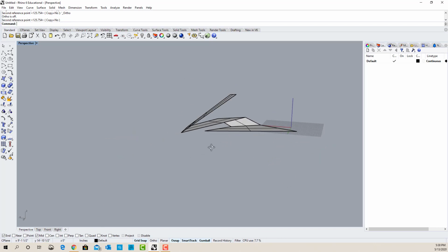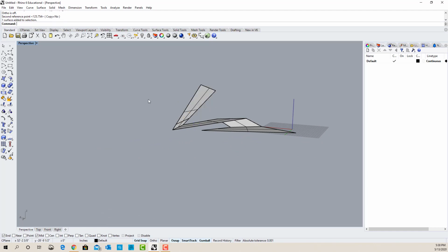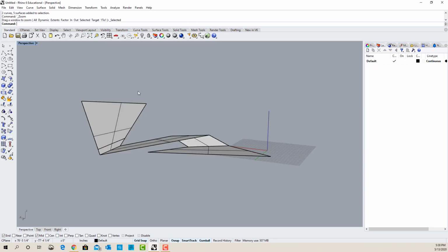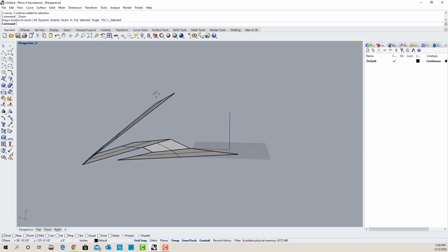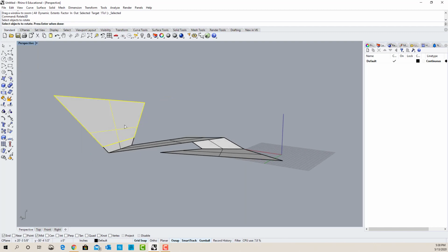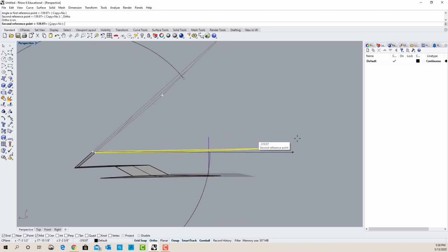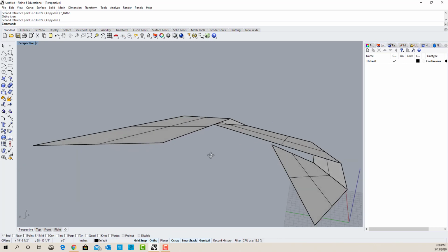And let's rotate again. Now we need to make this flat, parallel to this and to that. Let's zoom right there and rotate 3D. That's the hinge. And we're going to bring it from anywhere here flat. I just pressed F8 so it goes to 90 degrees, and there we go.